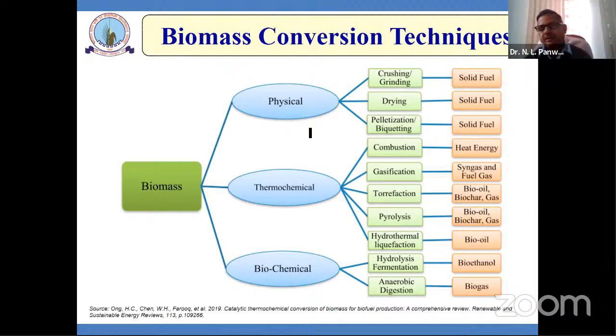During the torrefaction process, we heat the biomass, condense the gases, and make the biomass hydrophobic in nature. So it improves the grindability. Because we are dealing with crop residue, once you torrefy the biomass, it becomes hydrophobic and more brittle, so it improves the grindability. Once grindability improves, certainly the densified fuel will be better, with clean combustion. In the pyrolysis process, we simply heat the biomass, and the gas generated during pyrolysis is condensed and collected. So we are getting the bio oil.